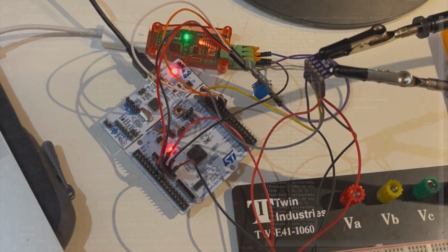Okay, so I just wanted to show you the hardware setup. Here we go. Yeah, so in purple, you can see the BMP280, the sensor. We have the STM32 microcontroller. So these two are wired through I2C. And then the microcontroller is wired to the CAN bus, and we can see there is a USB adapter. It's a USB to CAN adapter, so we can display the traffic of the CAN bus on my laptop.